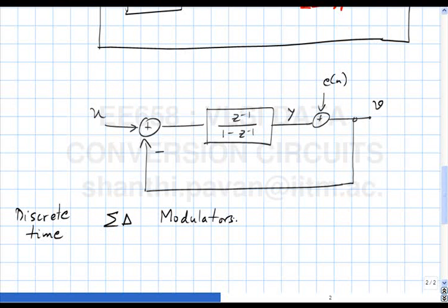All right, so digital audio was a big initial application point for a lot of these delta sigma modulators, because digital audio typically is 15 to 16 bit resolution. Professional audio is 24 bit resolution, right? And getting resolutions of the order of 15 or 16 bits with ordinary architectures is very difficult, because if you want to get 16 bit resolution, presumably the components that you use in making that A to D converter somewhere must have matching to better than 16 bits.